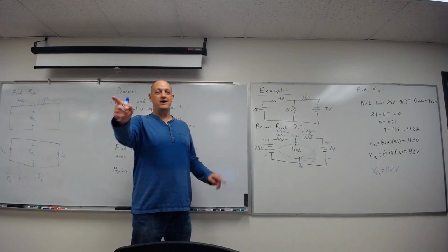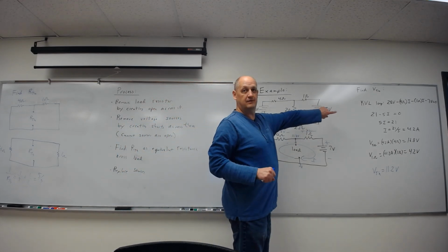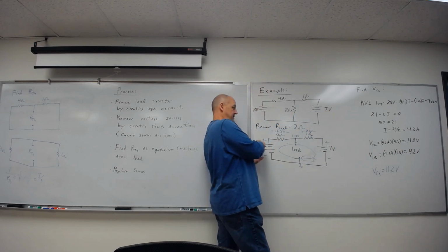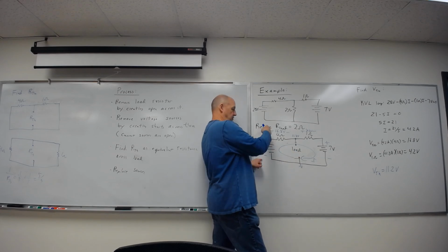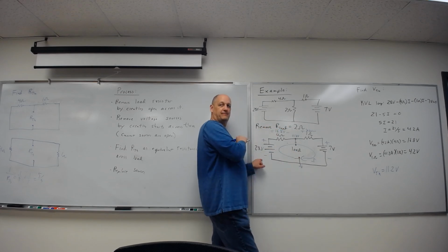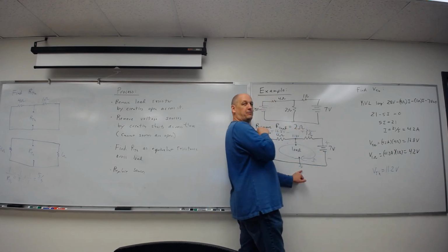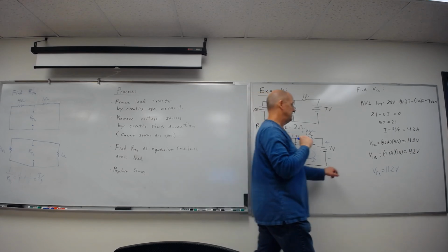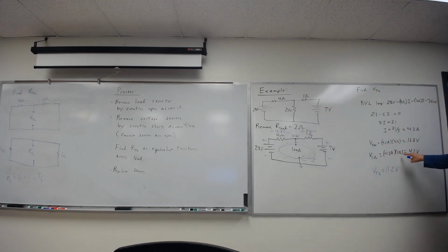We hit the fractions. Yeah, go ahead. Over there, how did you get 11.2 volts? I did 28 minus 16.8. Because if I start from this end, which is this side, I get to go up 28 and I drop 16.8. Or I can go from here and I go up 7 and I go up 4.2. I both end up with 11.2 volts. Where'd you get the 16.8 at? I found the current, and I just used the current to find those 2 voltages.